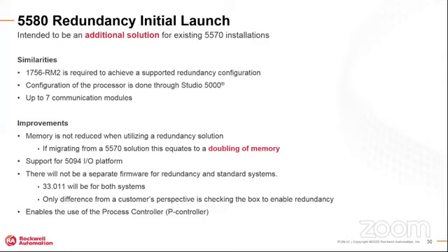That goes away as of the L8 style design. So when we're looking at that, one of the big selling features that we've had with the design change for just a simplex L8 5580 ControlLogix controller is the fact that you can use up to 100% of your memory, because all the communications and everything was handled off the separate core. So one of the things that we look for here is also the ability to now take advantage of that even during redundancy.